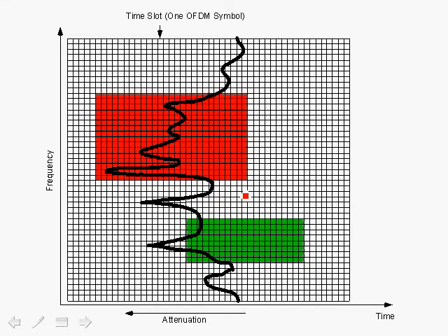Now, this slide shows an issue that may arise in OFDMA. We've shown superimposed over here the fading channel frequency response, and we show deep fades due to multipath fading in the channel. And if we consider that we are transmitting from the base station to multiple subscribers, and for now just imagine that we are transmitting to multiple subscribers, but we have a multipath fading characteristic that's shown over here, that each carrier may exhibit a deep fade and therefore loss of signal to noise ratio.